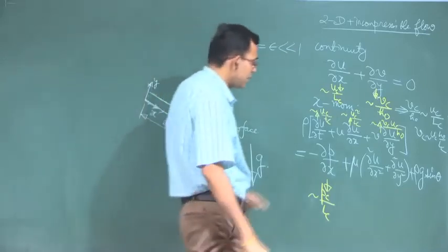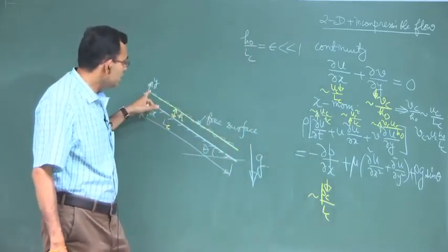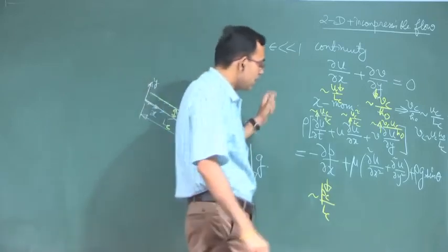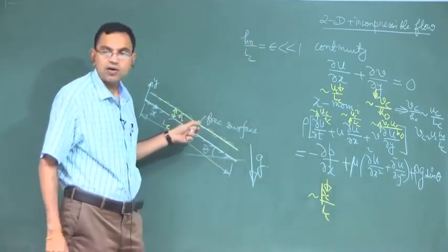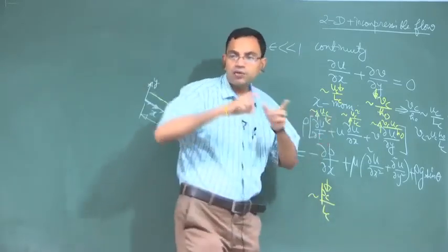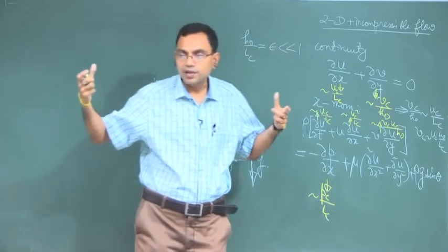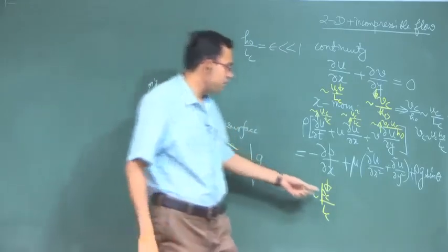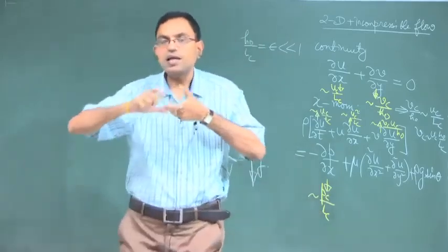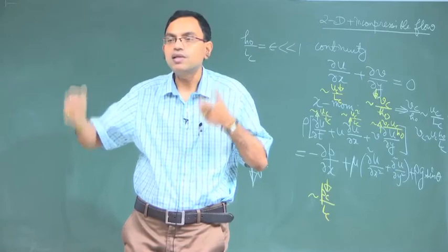First of all, Pc has to be important in all problems. The reason is that this arbitrary shape of the interface can be sustained with the help of a characteristic pressure difference across the two sides, and that makes the characteristic pressure important in this problem, where you have an arbitrary evolution of the interfacial topology, because it is the pressure difference across the two sides of the interface that allows it to sustain not only its static equilibrium shape, but also its dynamical evolution.